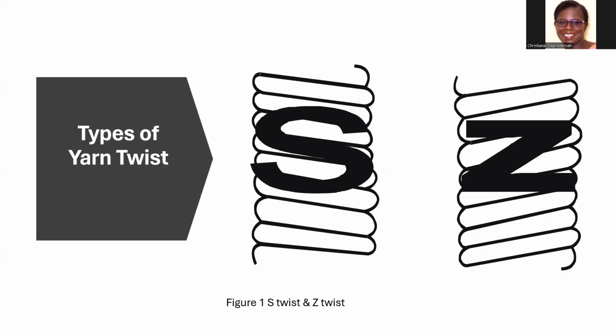The amount of twist you insert is very important, as I've already mentioned. With low twist, the turns are very few, giving fewer turns per inch, and that produces soft and fluffy yarns. That one is used for knitting, like crocheting yarns.